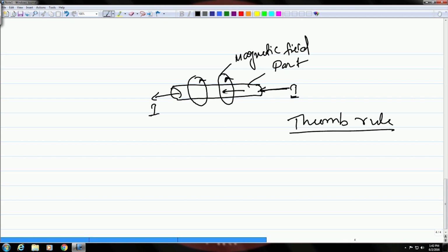So, when you flow a current like this on a part, it produces a circular kind of magnetic field, the direction of which, as I said, will depend on the direction of the current, and using this circular field you can magnetize the part by directly flowing the current through it.